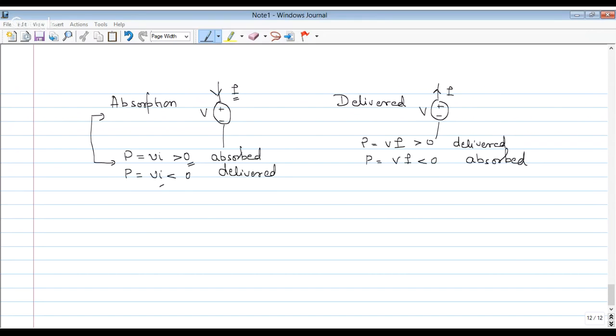But mutual flux does not change. Why? Because that component is cancelled using primary current. But leakage flux will change according to the change in the total supply current. Is it fine? Coupling coefficient depends on the winding orientation.